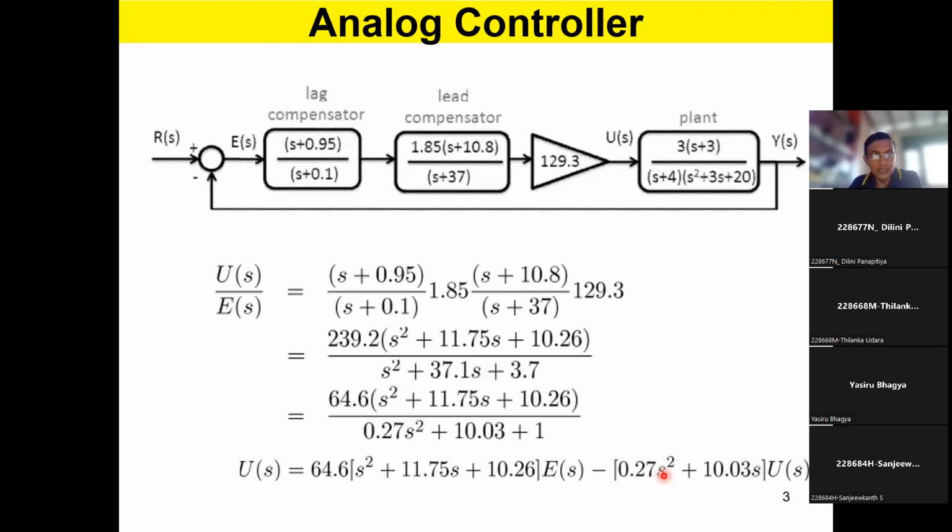And of course, it's also very easy. If you want the first derivative, it is y(t) minus y(t minus 1), the previous sample. If you get the sample now and the sample from the last time you read it, you take the difference divided by time. So that is differentiation. And the second derivative can also be done in a similar way.